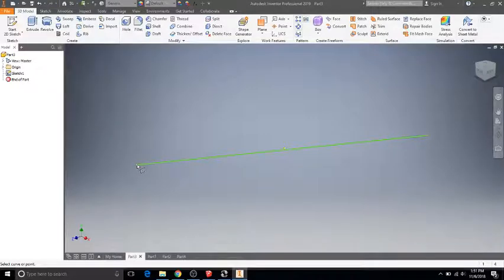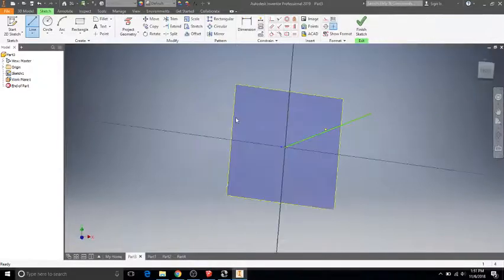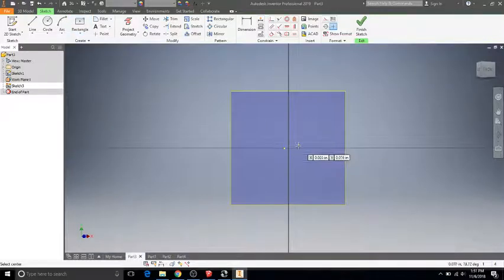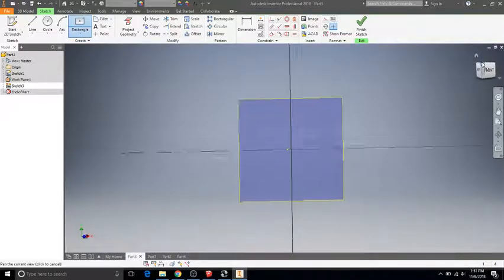If you select plane, normal to curve at point, which is the very bottom option, double click here, then what it does is it creates that spinning plate, so to speak, and the line is like your finger spinning the plate. So now you have to create the profile. You interact with work planes by clicking on the edge. You're going to create a sketch, and I'm going to do a rectangle that's centered, 2-point rectangle. I'm going to center it on that line.